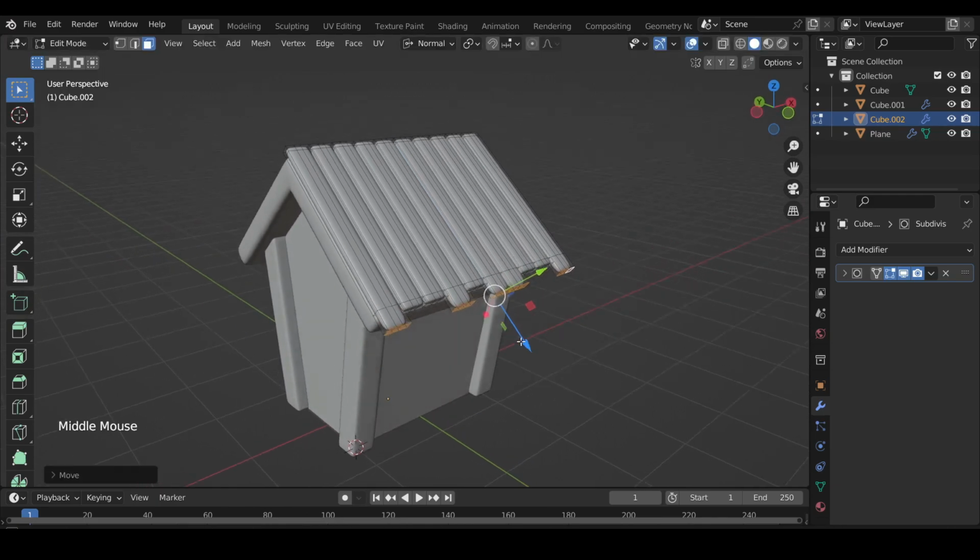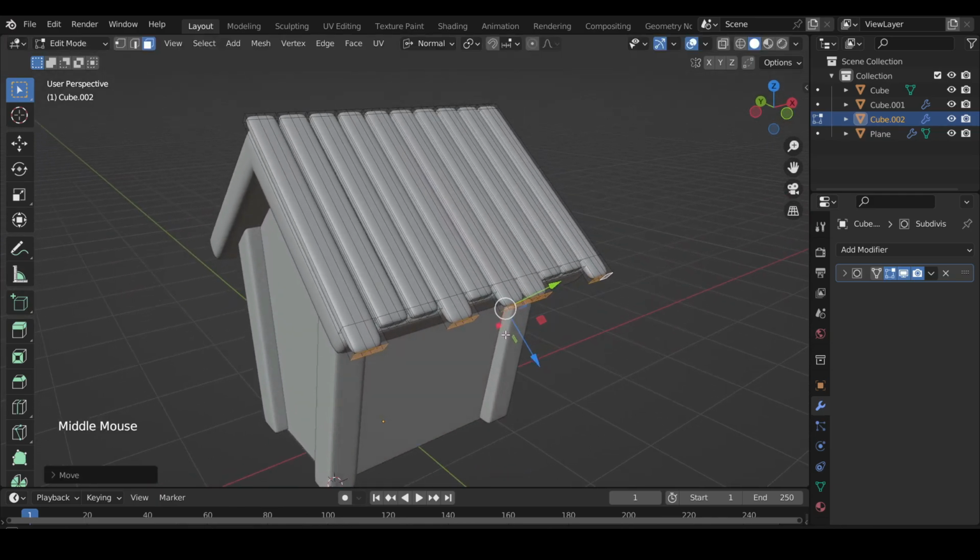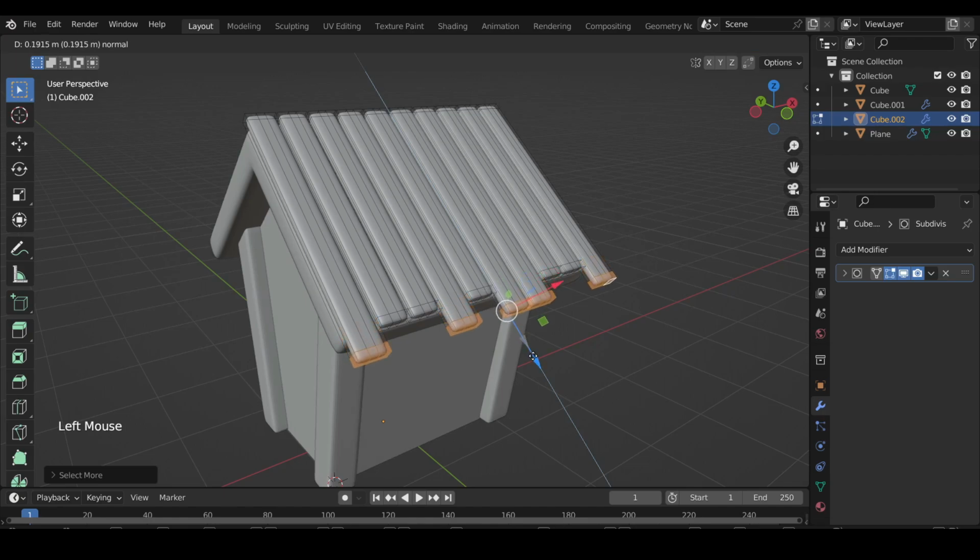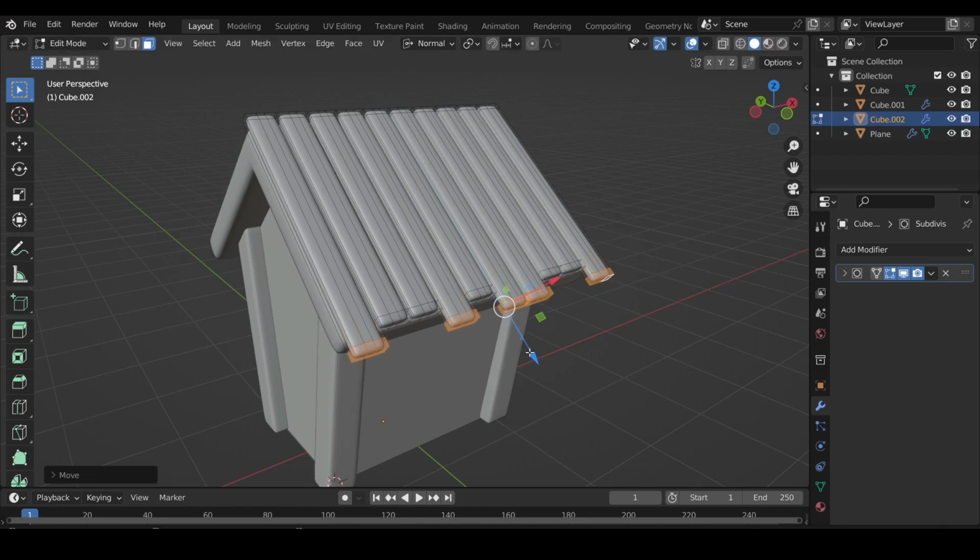If you do this, you will then also need to select the control loops on each of them, and bring them down too. However, let's undo this step, and use Ctrl and numpad plus button to increase the existing selection, and drag down. If you don't have a numpad, you can head over to the Select menu and select More under Select More or Less.